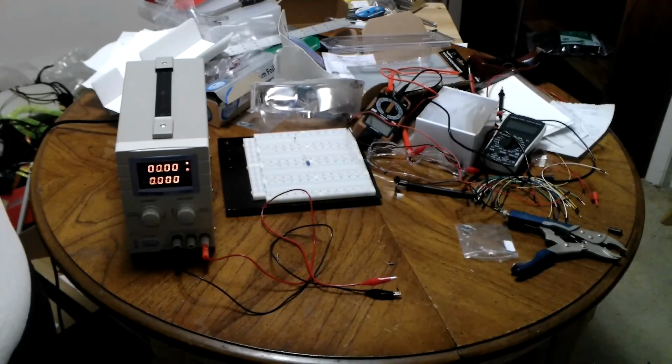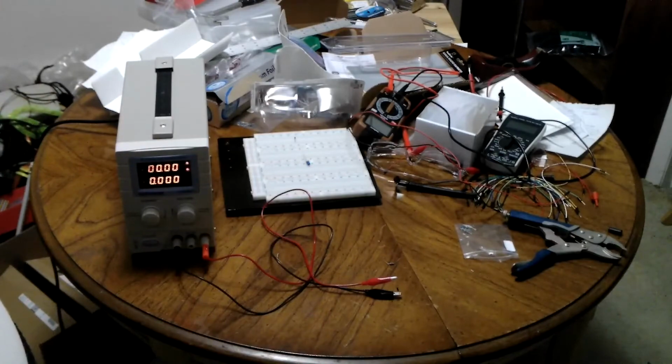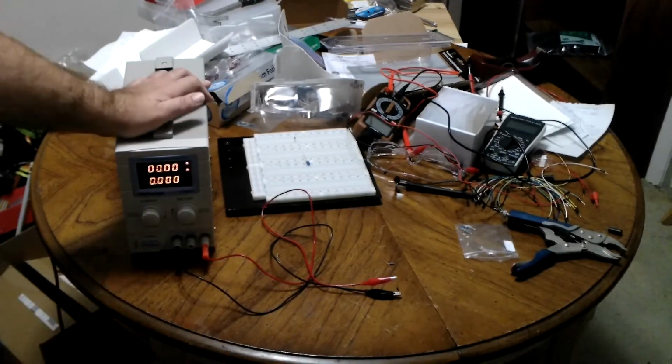1/4 watt is the number they give you that you should be aiming for to keep that resistor going for the lifetime of the device. So always obey your power limits. So that is basically all of the math you need to know to build very simple circuits, as long as you're following good directions. In order to build more complex ones where you have to analyze the flow pattern of current throughout the device, that's only half the math you need.